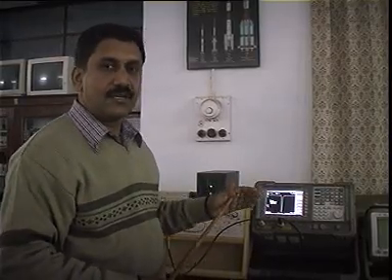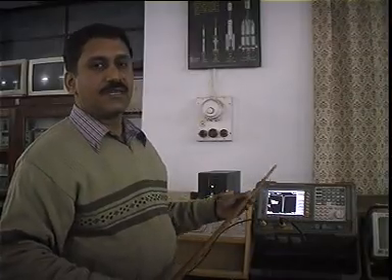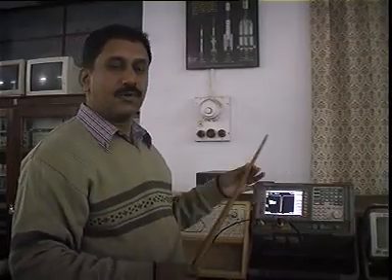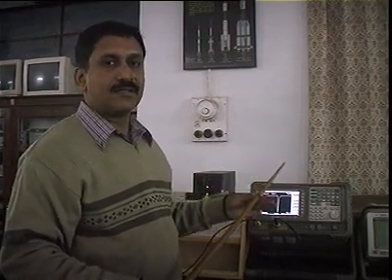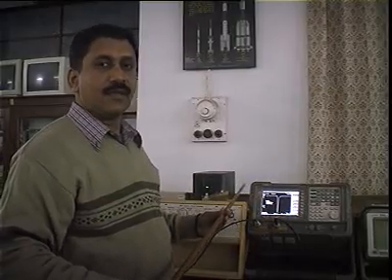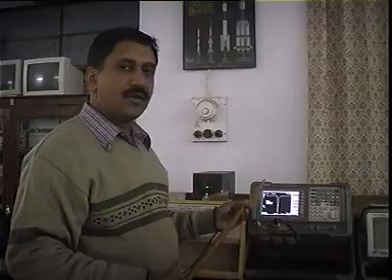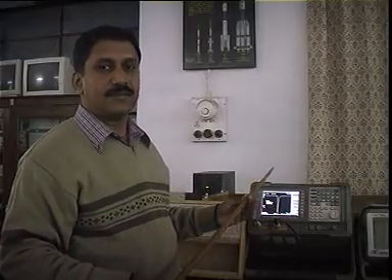To characterize a filter using a spectrum analyzer, you will need a spectrum analyzer which has got a built-in source which can give you a broad band of frequencies. You input those frequencies to a given filter, and then connect the output of the filter to the input of the spectrum analyzer. And on screen you will be able to record the frequency response of the filter, and from there find out various parameters of the filter.